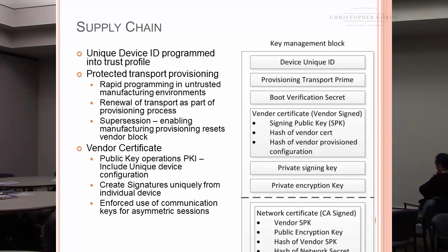And then secrets of boot verification connect really close to the configuration. So you take the base memory block, you hash it with the boot secret, and you produce a signature, and that signature then goes along with the firmware. It won't operate unless it has a signature. And this all has to be thought about and designed into the design stage of the devices,